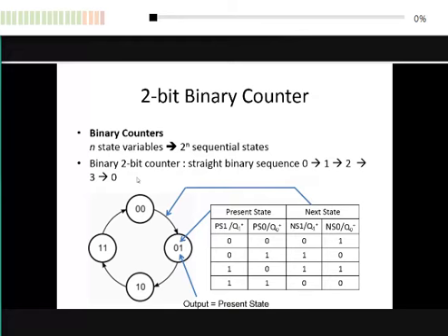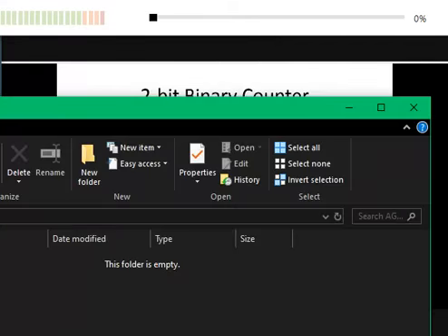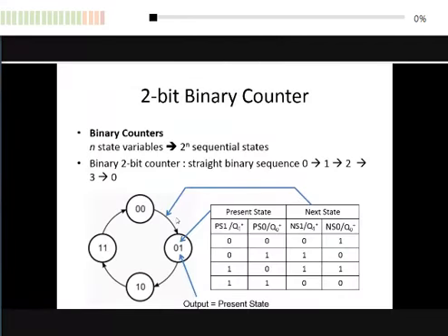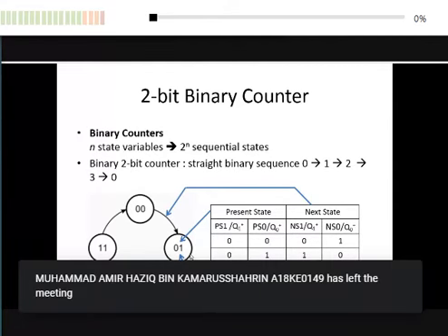It's a continuous process, and you see on the arcs there is no input at all, no label, either 1 or 0, no input labels. It means that this is unconditional, as long as there is a clock. That's what the arrow tells. When a clock occurs, it will change to the next state. Another clock occurs, it will change to the next state, and so on.